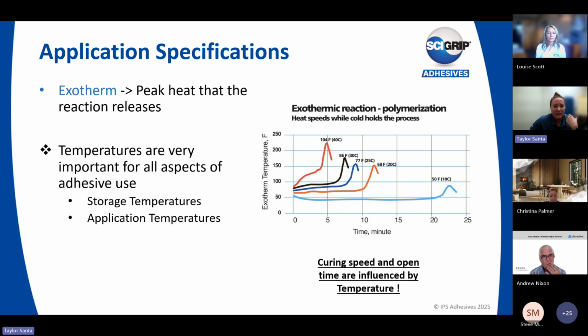The last thing really we want to think about in regards to temperature is the external or environmental temperatures. These environmental temperatures will have an effect on the working time and also the shelf life of product. If adhesive cartridges or bulk material is left in very low temperatures for a long time, the activation chemical found in the activator side of the material will come out of solution really. It'll almost crystallize, and you'll be able to actually see it in the activator side. Once this material is out of the solution, it won't go back in, and the adhesive material won't cure properly. You'll see spotty cures, soft cures, essentially ruining any material that you have.